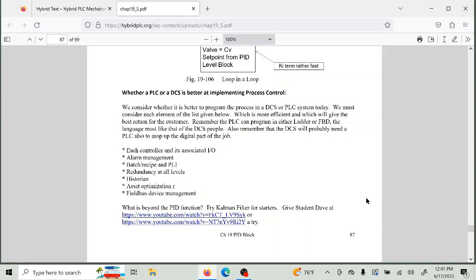You've got three areas. You've got the diagnostic or alarm area, you've got your control area, and you've got your HMI area. And they all three have to be changed if you make a change in one of them. So you have to be careful. You have to realize that, and you have to move together. Sometimes maybe you can put variables together so that you can do that automatically, but many times you can't, and you have to guarantee that if you make one change, you make it across the board in all three areas. That's why DCS people argue that they're more sophisticated and better, because you don't have to worry about that. You just make the change one place and you've automatically got all those changes ready for you.